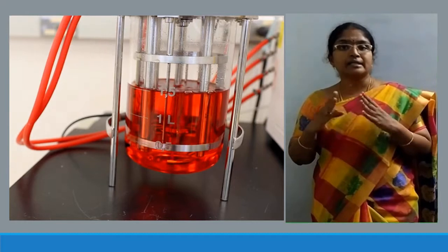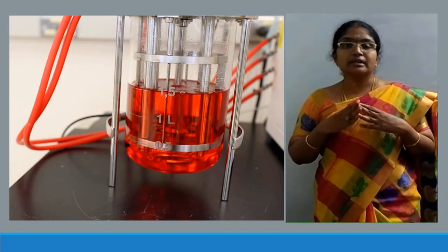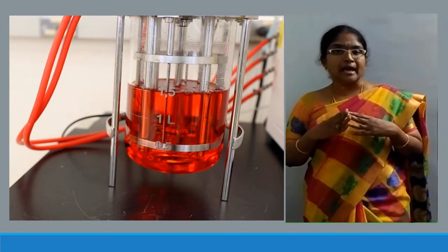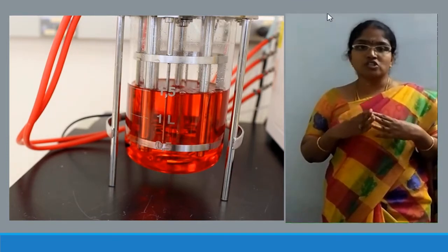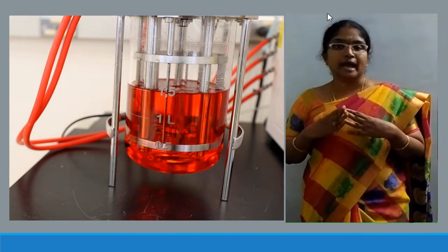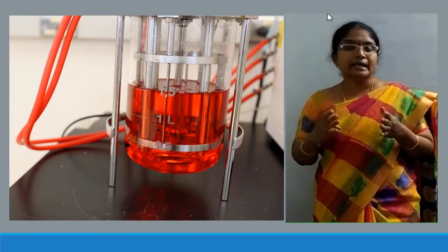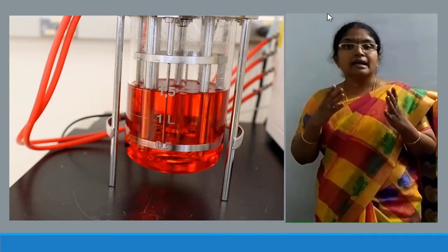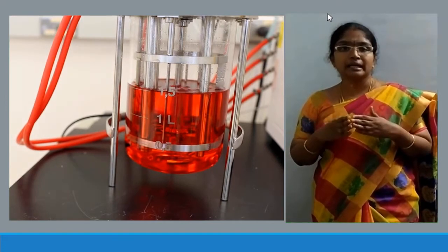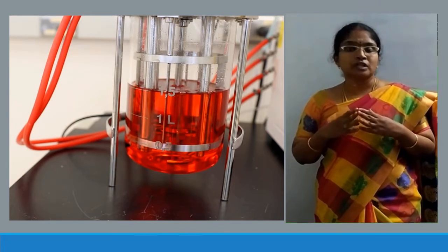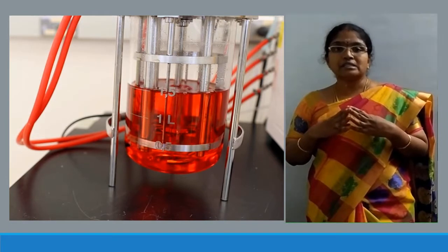A bioreactor is a vessel where the gas is passed into the reactor so that the oxygen present in the air will be readily utilized by the organisms. This oxygen being fed into the reactor will take some time to get dissolved and be readily available, and it is mandatory to estimate the dissolved oxygen concentration in the reactor so that the optimum concentration of oxygen will be available for the organisms to grow.